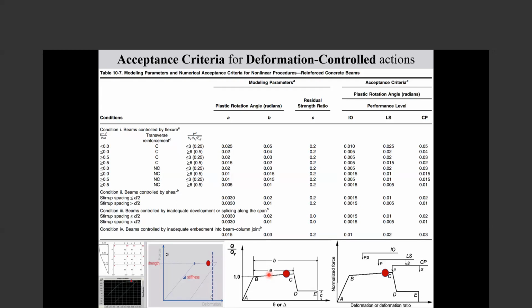The same software that is prepared now for doing nonlinear analysis can be used for new buildings. It is just a matter of the code developers and the code authorities to let it be used, and in what areas they let it. For example, if you use the approach for existing buildings, you can omit the need for the R factor.